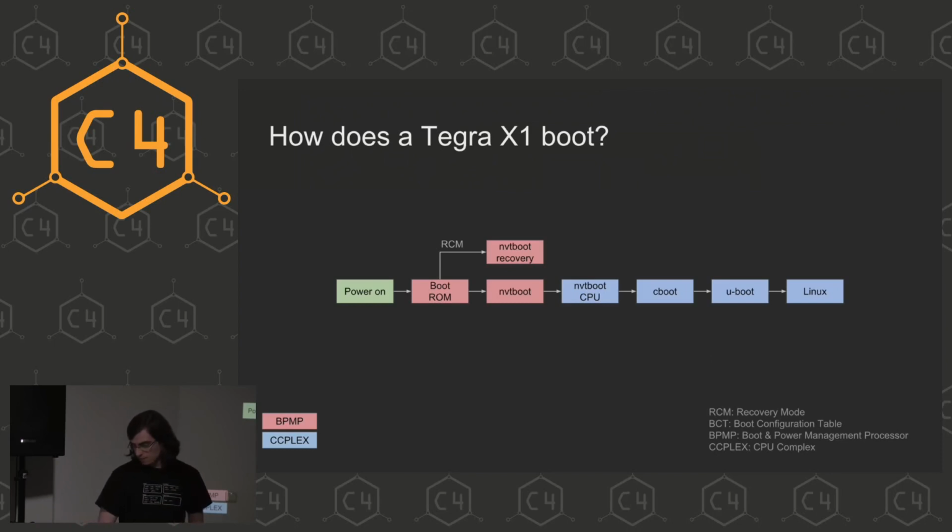Yeah. The boot ROM itself, what it does is does a bunch of things. First is basic hardware bootstrapping. It has to configure some PLLs, so everything on the chip has clocks to work with. Then it determines what to do, either boot into RCM or do a warm boot or where to load the bootloader from. It does this by looking at so-called fuse bits, configuration bits that you can only write once and then afterwards read.